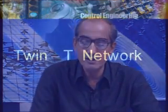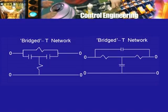It is possible to think of one more network which is a little more complicated, which is called a twin T network. A T network is what this looks like, a T, right? This capacitor arm, another capacitor arm and a resistor arm, this is a T, this is another T. Now, you can connect these two T's in parallel, so to speak, in parallel at the input terminals, in parallel at the output terminals, and you get a twin T network. You can find out what will be the transfer function of a twin T network. Of course, it will be a little more complicated, it will involve more calculation and so on, but you should try this out on your own before you look up any expressions which are given in your textbook.